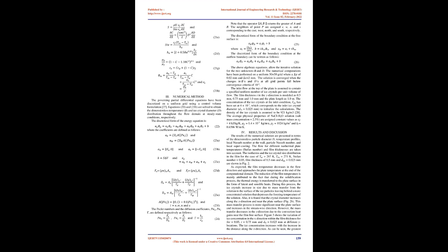The experimental results presented by Sohn and Chen [23] were used to evaluate the constants B and M at moderate Peclet numbers and assign them values of 1.8 and 0.18, respectively. The heat generation rate per ice crystal is given as (9), where h_IF is the latent heat of the liquid solvent. Then the source term S in the governing energy equation can be computed from (10), where N is the number of ice crystals per unit volume.